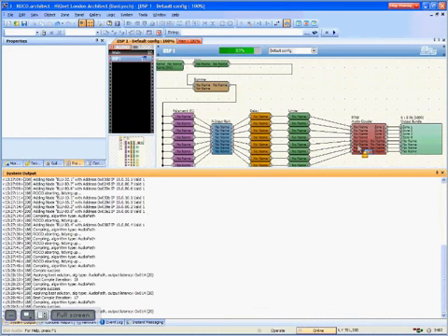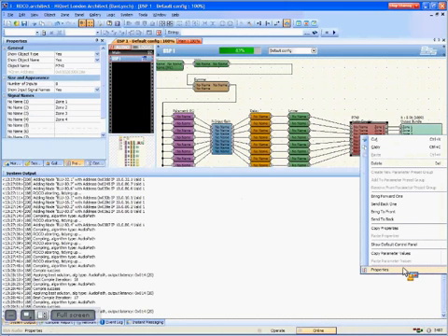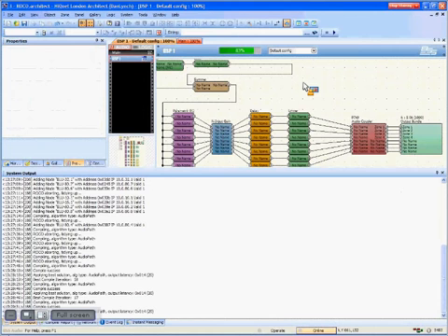Okay, so we looked at the audio coupler, which is really cool. Change signal names, that is so cool. You can drop it down to one channel, have up to 32 channels. You've seen me a couple times today go right-click, properties. That's new in version 2. That didn't exist before. For anybody who's used a wall pot volume control in the past and bumped up against the fact that there's no way to sub-range limit volume of that wall control, well, now there is.